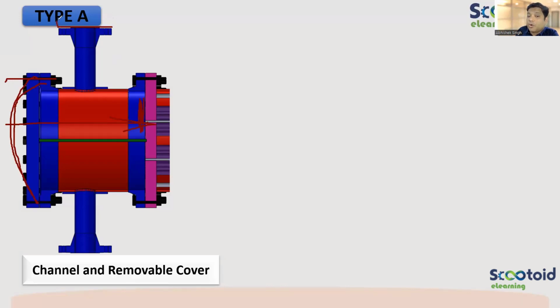These two nozzles will be connected through pipe, right? Again, there will be a nozzle, and then there will be a flange and then the pipe connected. So I don't have to unbolt from here. I can do mechanical cleaning by just unbolting this bolt. I can go inside and clean.